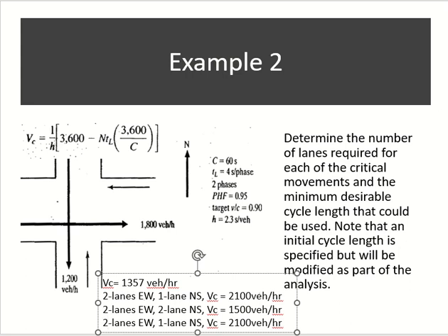East-west, because one lane is carrying 900 still. So if I make three lanes, total was 1800. It will be divided into three lanes, so 600 each lane, right? And north-south is still two lanes. So 600 from there, 600 from there. 1200. Problem solved or not? Why would we add opposite directions with each other? Because this is for the entire signal, for the entire cycle. In one cycle, both directions have to go at some time, right? This is the total of both phases. Clear?